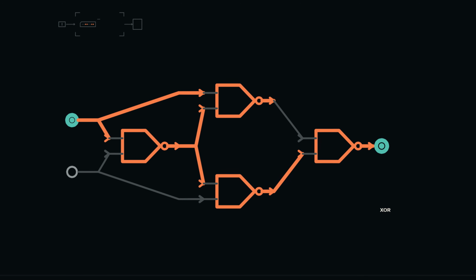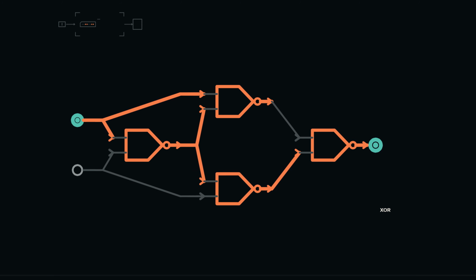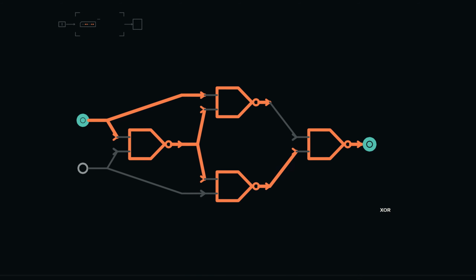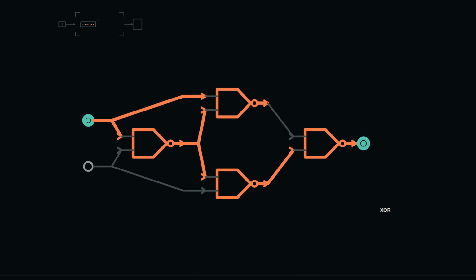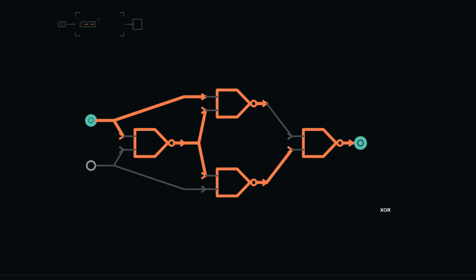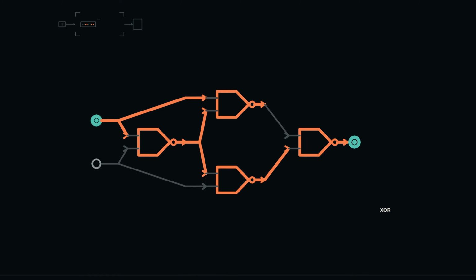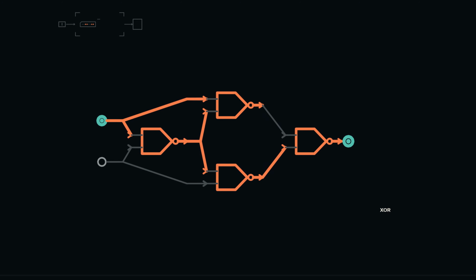One last network arrives without a label. Its first stage makes NAND of A and B, and its second stage inverts that result. Predict the output for all 4 rows. Only one survives as 1, the other rows become 0. That is, AND. The test matters because it asks you to recover a contract from operations rather than recognize a familiar outline. If the internal routes are traceable, a new arrangement is a problem we can solve, not a symbol we must memorize.